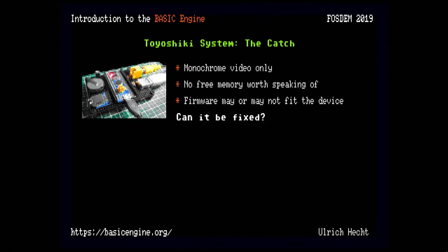Can we do something about that? I tried to add hardware, like simple hardware that doesn't cost much, to generate color. That is unfortunately a bit tricky with analog video. You need to basically mix a high frequency color burst signal on top of the monochrome signal, and I used all sorts of tricks, and some of the timers of the STM32 chip. It's very capable hardware, but that consumed a lot of resources.